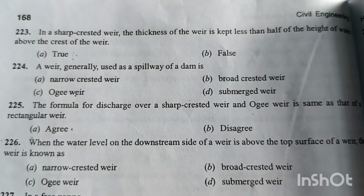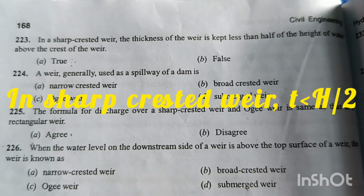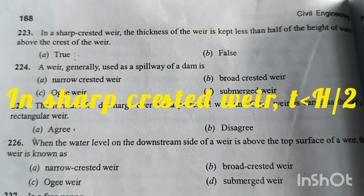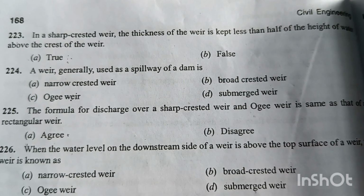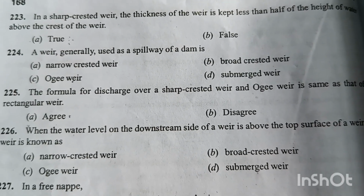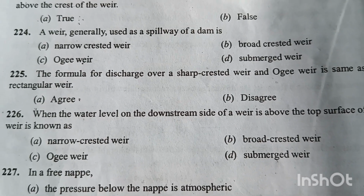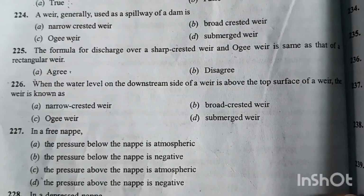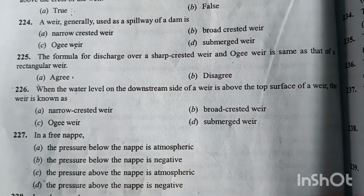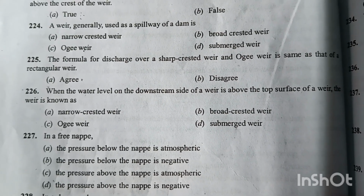Question number 223. In a sharp crested weir, the thickness of the weir is kept less than half of the height of the water above the crest of the weir. Option A is the right answer. True. Question number 224. A weir generally used as a spillway of a dam is an ogee weir. Option C is the right answer. Question number 225. The formula for discharge over a sharp crested weir and an ogee weir is the same as that of a rectangular weir. Option A is the right answer.